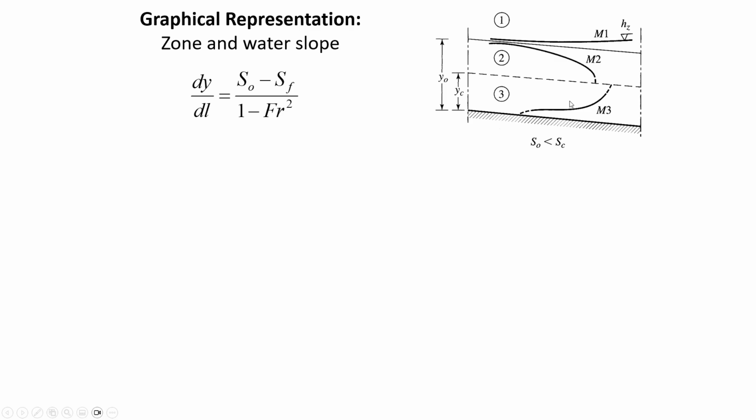We saw it in the hydraulics lab. An underflow gate. Yeah, M3, it's what you'll see before the hydraulic jump occurs. So you've got a mild slope, but if the water is down here in zone 3, that means that you've got supercritical flow on a mild slope. So an M3 profile is on its way to a hydraulic jump.